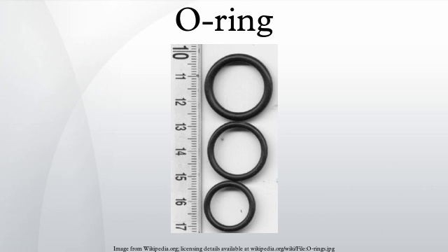Typical applications: successful O-ring joint design requires a rigid mechanical mounting that applies a predictable deformation to the O-ring. This introduces a calculated mechanical stress at the O-ring contacting surfaces. As long as the pressure of the fluid being contained does not exceed the contact stress of the O-ring, leaking cannot occur. Fortunately, the pressure of the contained fluid transfers through the essentially incompressible O-ring material, and the contact stress rises with increasing pressure. For this reason, an O-ring can easily seal high pressure as long as it does not fail mechanically. The most common failure is extrusion through the mating parts.